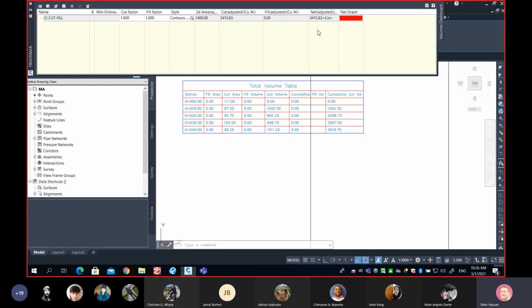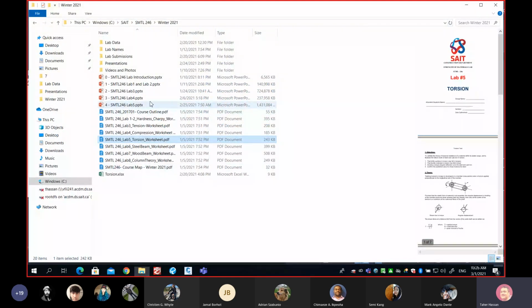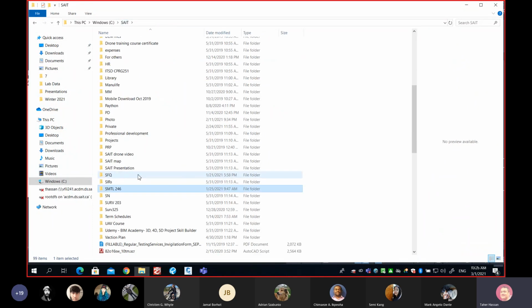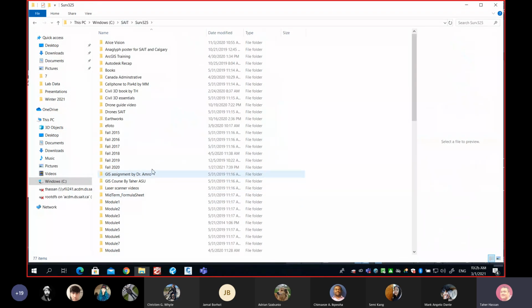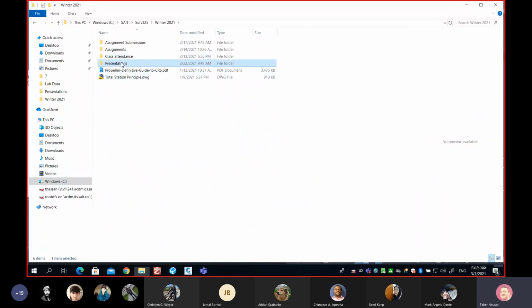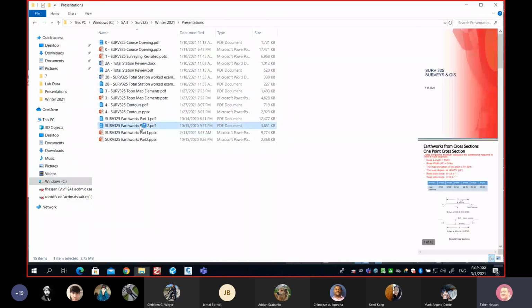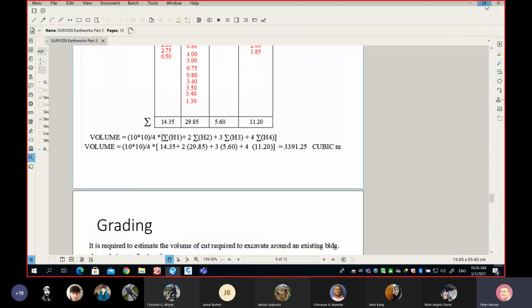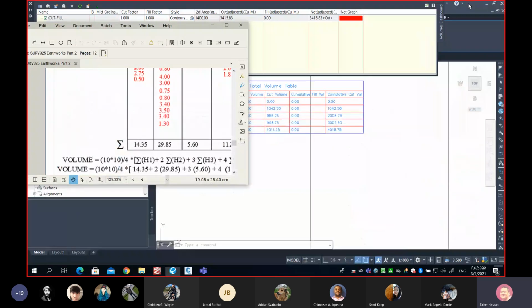You can see there is about 600 cubic meters difference between whatever we get from the cross-section method and the volume dashboard. And again, if you also want to remember, what's the number we got manually? You guys remember, huh? The number we got manually is here. So this is the number manually. I'll open the file for you and put them side by side, everything together in one.